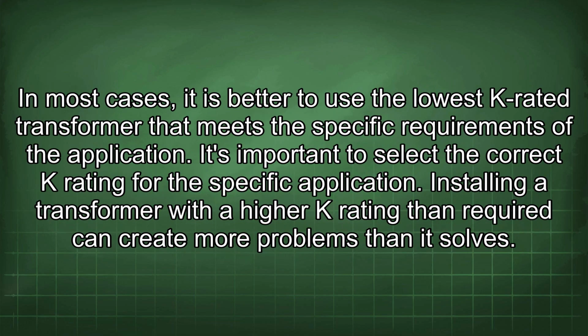In most cases, it is better to use the lowest K-rated transformer that meets the specific requirements of the application. It's important to select the correct K rating for the specific application. Installing a transformer with a higher K rating than required can create more problems than it solves.